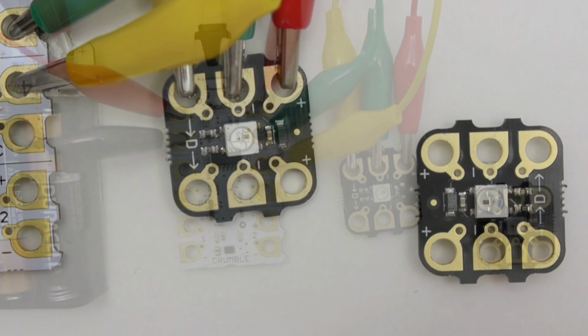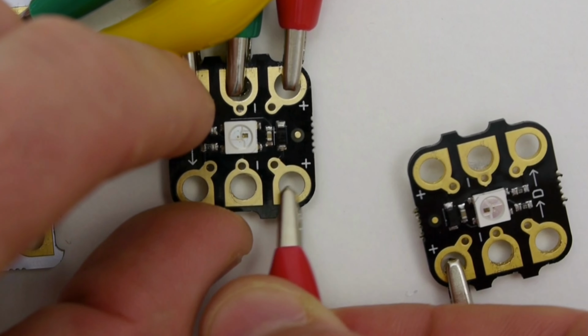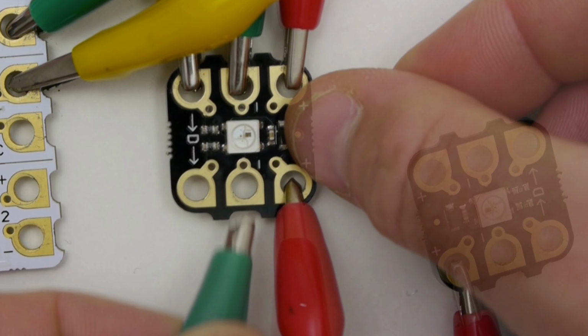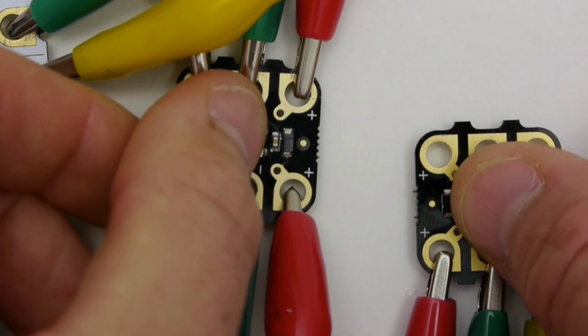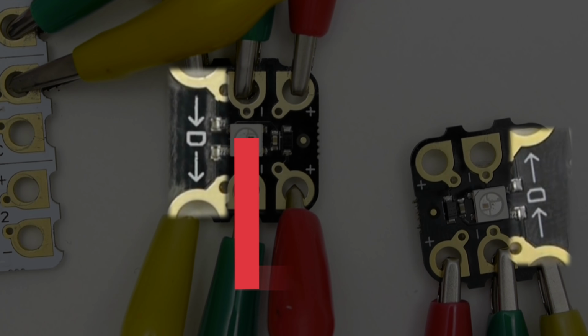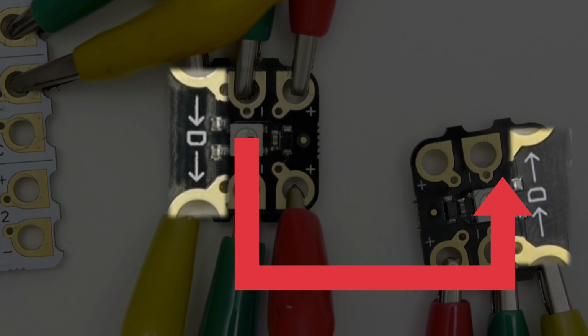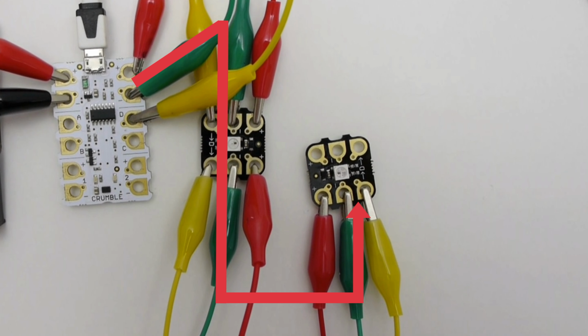The second sparkle is going to need power, provided by the positive and negative wires that attach to the other sparkle. And it's also going to need a digital input so we can tell the sparkle what to do. We'll wire that up like this. Notice how the arrows on the sparkles show how the power and the digital signal flow from one sparkle to the other. It's important these arrows are the right way round, flowing away from the crumble.